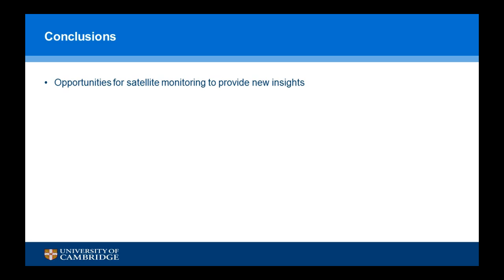Every 2 years, you have a general inspection where you can physically see the bridge, and every 6 years we're actually close enough to touch it. So in that period between the 2 and 6 years, you have a data source giving you some kind of insight and understanding. And also at a time where we're seeing increased changes due to climate change and a number of different anthropogenic effects, it gives you some kind of insight in between these readings.